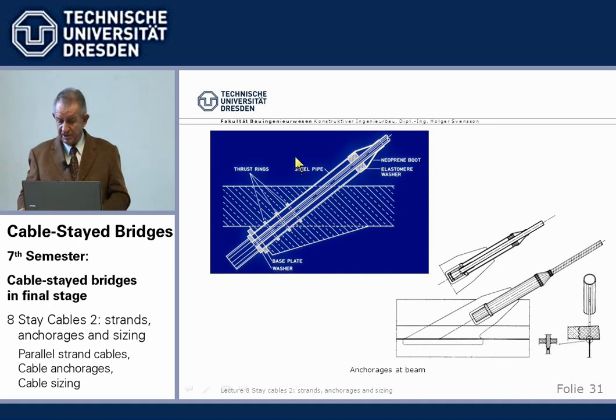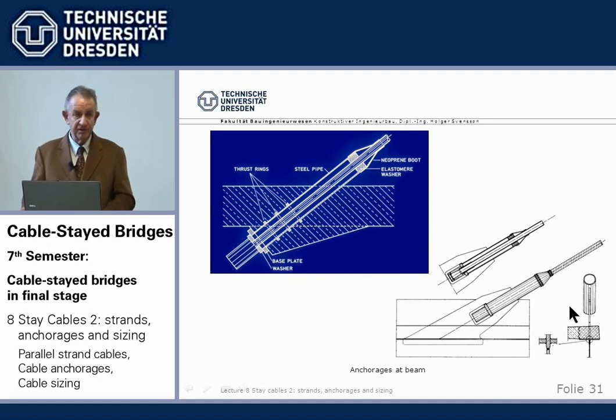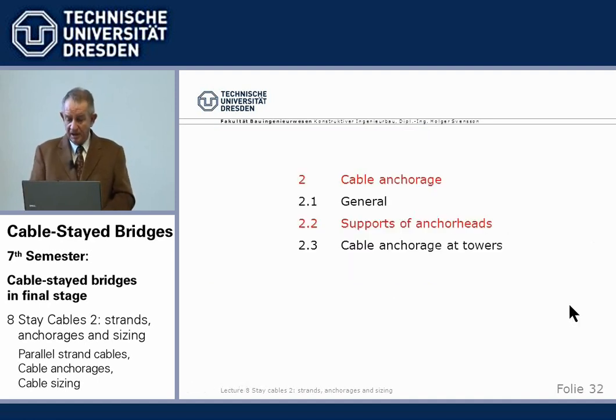What you do is you make a pocket: you cut a slot into the top flange here, like this, stick the new plate through, and then make a butt weld here. And this butt weld has the same strength, fatigue strength, and so on, as the rest. So that's a little detail, of course, you have to take into account.